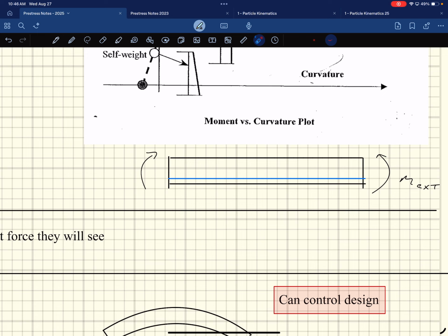Because it's like, oh, because this is pre-stress. It turns out it's very little. How much it changes when it bends is very little compared to how much we stretched it originally. So we stretched it almost to 270 KSI, and then when you apply a little load, it just makes it move just a little bit. It doesn't actually affect the overall load very much. But when I first learned this, it always threw me off a little bit. It's like, why? It does elongate when you bend it, and so the pre-stressing forces will go up, but we ignore it.